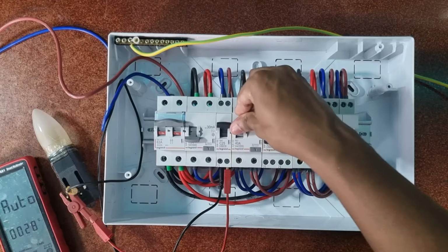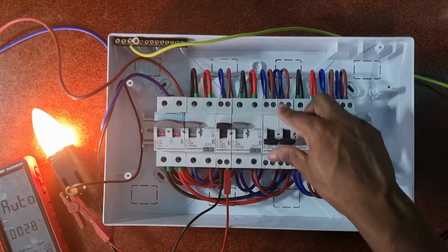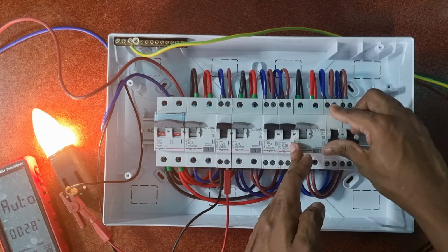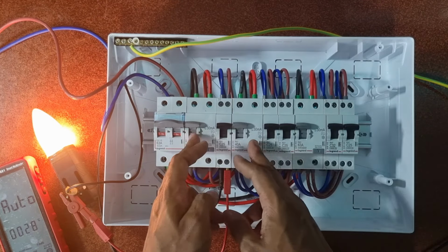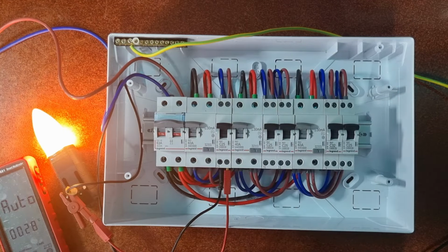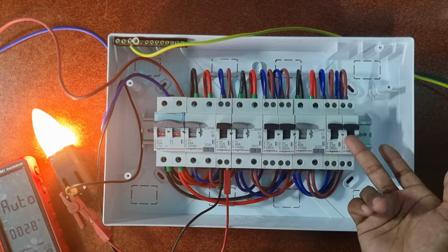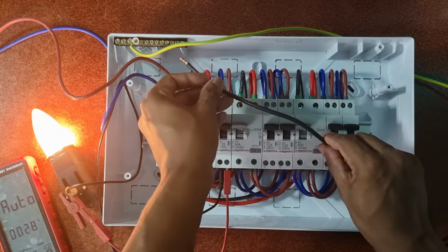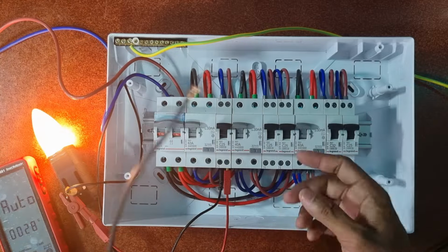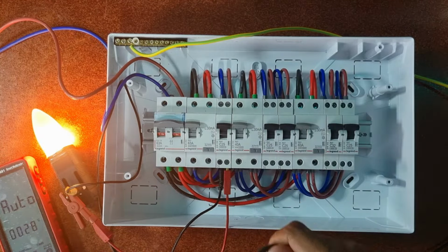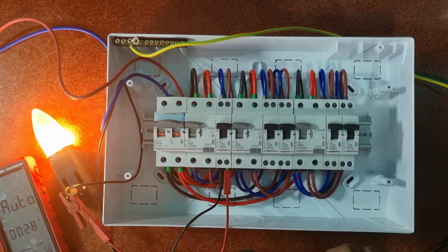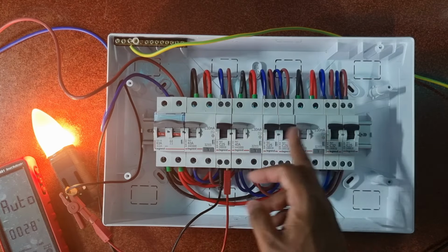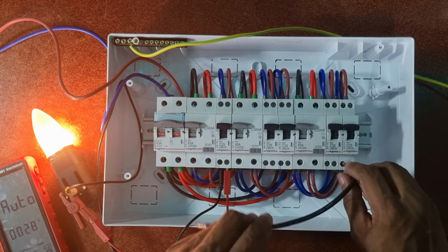Now let's say everything is on. Remember, this one controls these two breakers and that one controls these two breakers. So I separate everything. Now let's say we have a fault in, I don't know, the kitchen. Let's touch kitchen neutral to earth. So which one will trip? Can you guys answer me in the comment real quick? Or you can pause the video and type your answer. Which RCD, 1, 2, or 3? Okay, I'm going to do it right now.